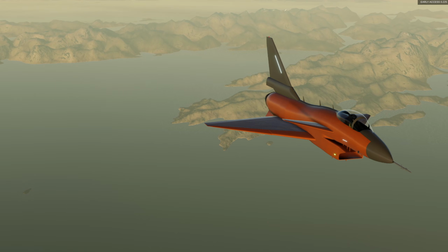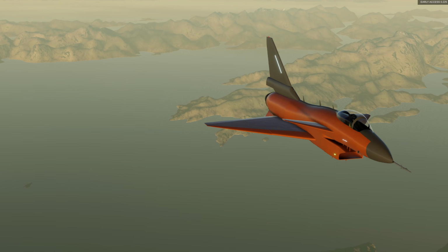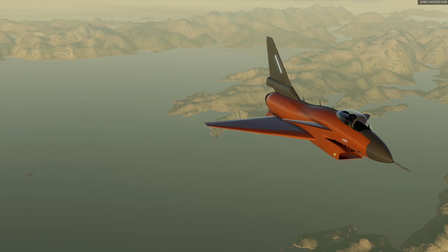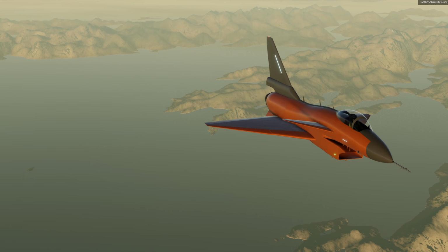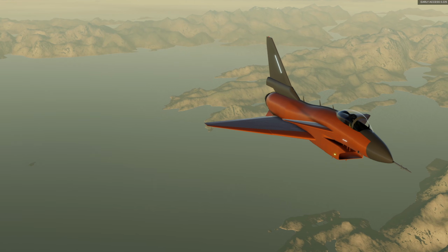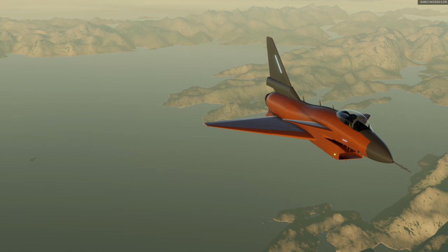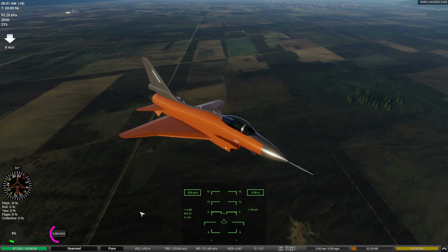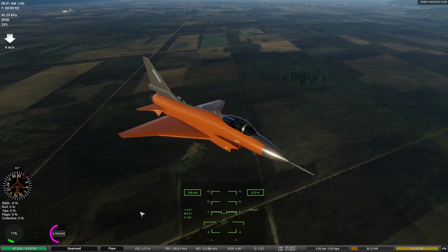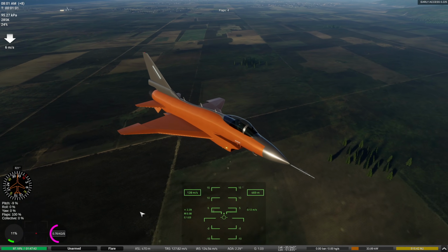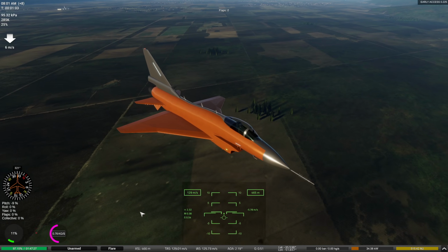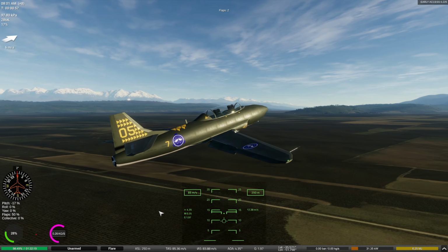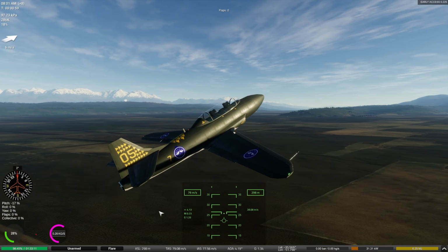There are other types of flaps in high lift devices such as split flaps, and slotted Fowler flaps that help remedy the flow separation issue that plane flaps have, but they are unfortunately not currently available in Flyout. Deploying flaps will also cause a downwards pitching moment on the airfoil, though whether or not your aircraft pitches down with flaps deployed depends much more on the location of your wings relative to the center of mass. Placing the wings too far ahead of or behind the center of mass will cause a significant upwards or downwards pitching moment, respectively.